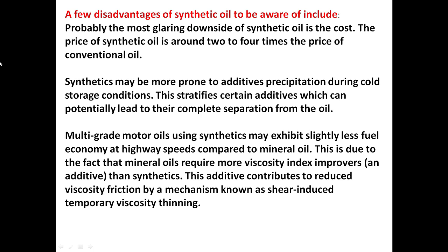Multi-grade motor oil using synthetics may exhibit slightly less fuel economy at highway speeds compared to mineral oil. This is due to the fact that mineral oils require more viscosity in extreme grades than synthetics. This additive contributes to reducing viscosity friction by a mechanism known as shear-induced temporary viscosity thinning.